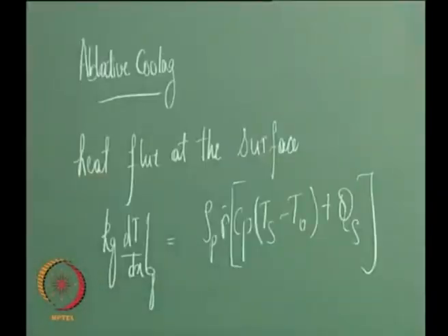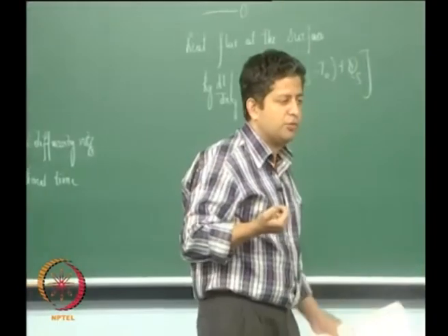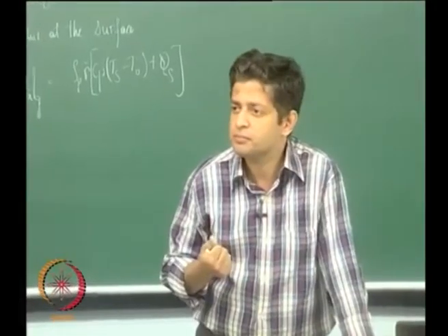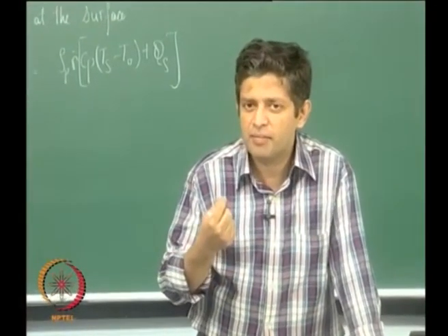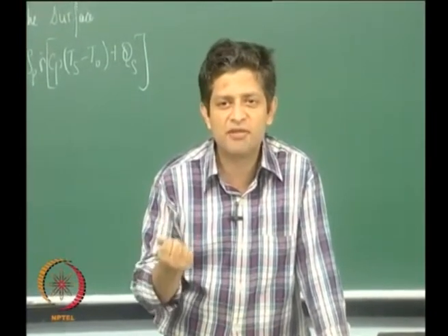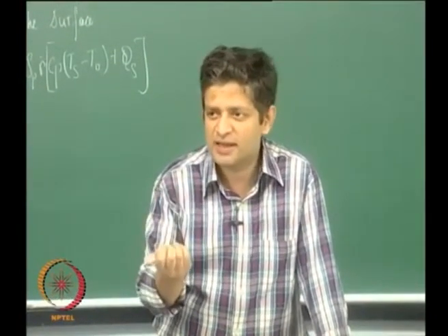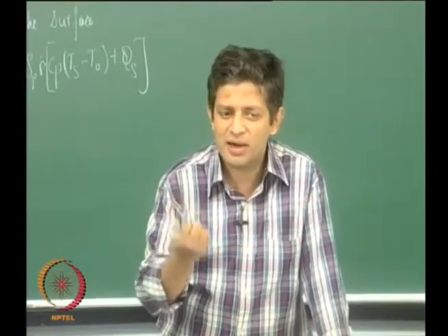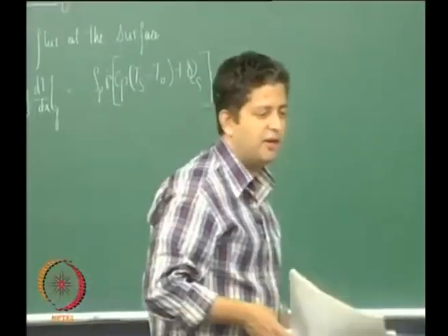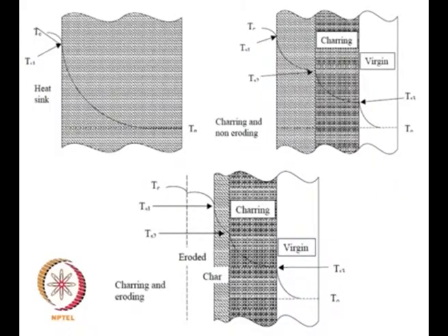Right. Now, if you are looking at this ablative cooling, what happens here is there is this resin portion that vaporizes. So, it absorbs heat to change its state from solid to a gas phase. Okay. As this heat is absorbed, it cools the rest of the material, and there are two kinds of heat resistant ablative cooling techniques that are available.